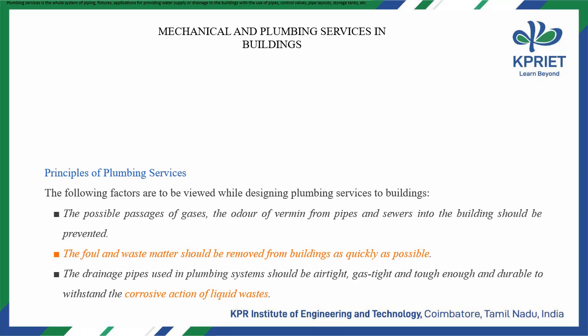Principles of plumbing services. The following factors are to be viewed while designing plumbing services to buildings. The possible passages of gases, the odor of vermin from pipes and sewers into the building should be prevented. The foul and waste matter should be removed from buildings as quickly as possible.